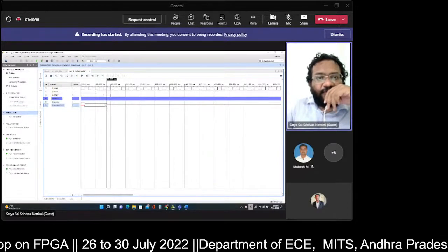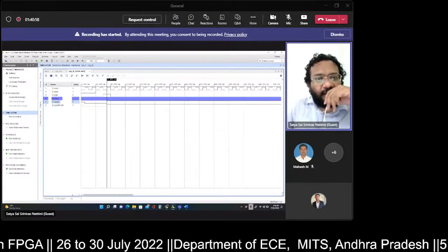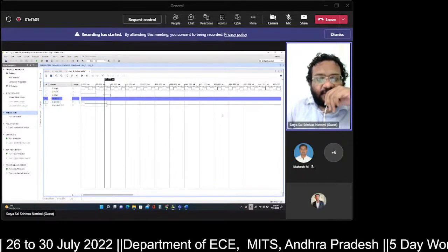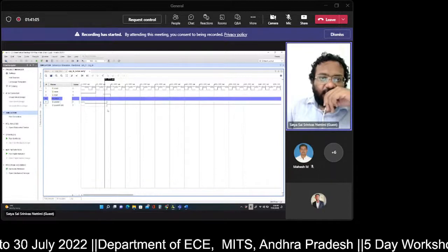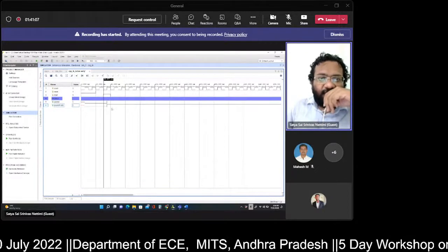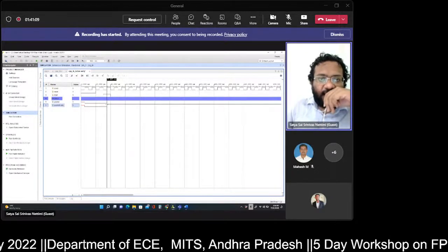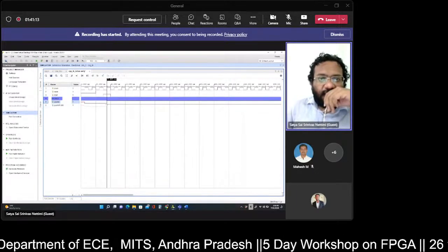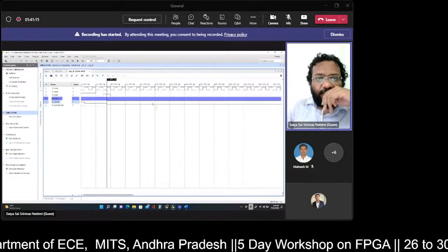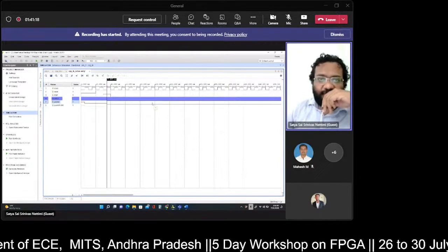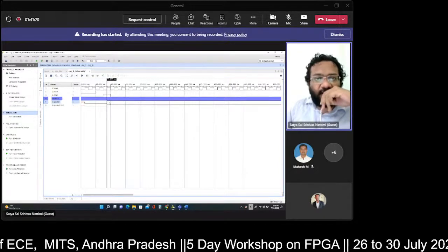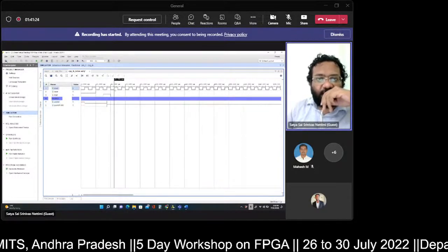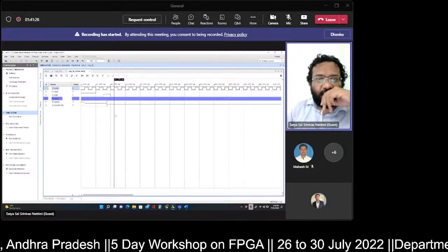From there we read the output called packet, and we will get the actual packet sequence. The moment the packet valid is logic high, we got a packet value of 1. I think this is the first bit, and this input is valid for 1 clock cycle, up to here.